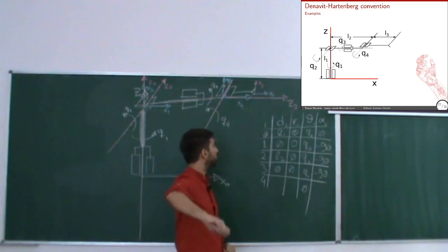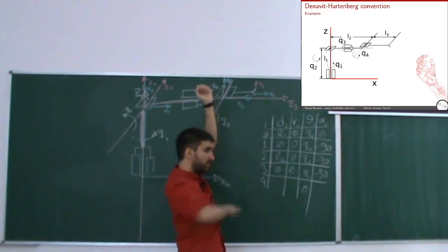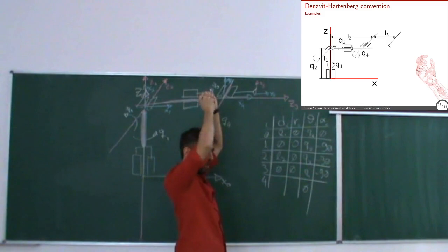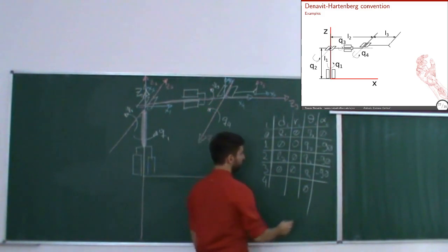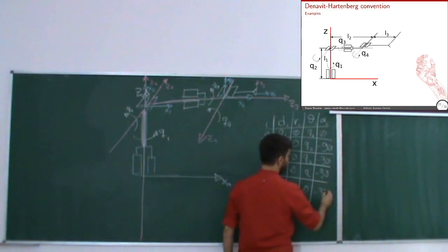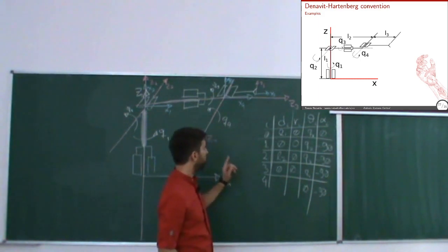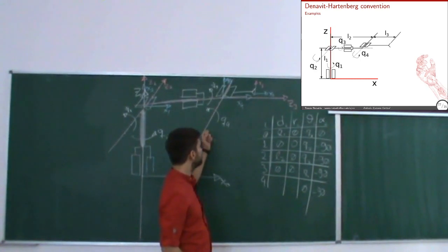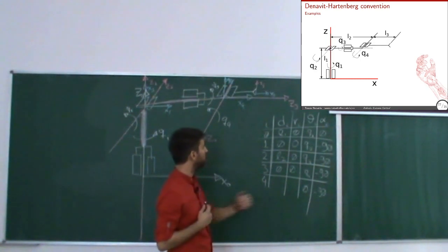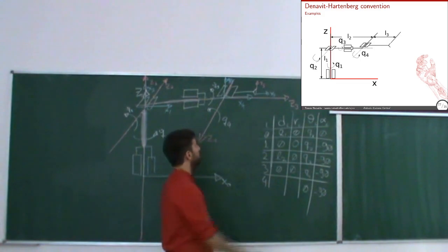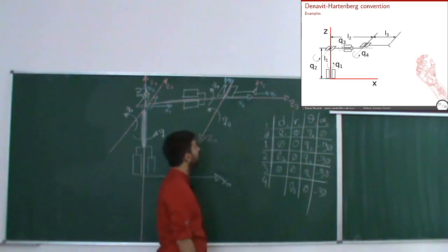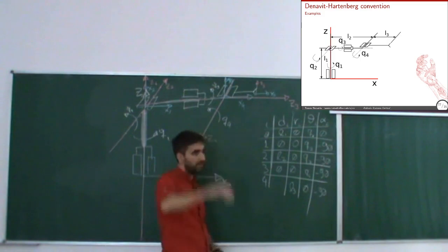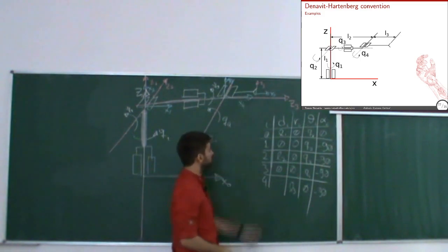So Z4, Z5, x4, this angle, minus 90. The distance between Z4 and Z5 along x4 is this length here, L3. And the distance between x4 and x5 around Z5, if we consider this to be a line, it's 0.